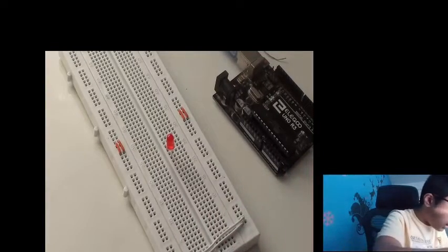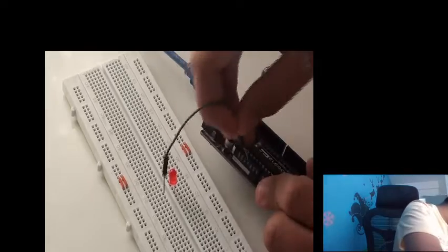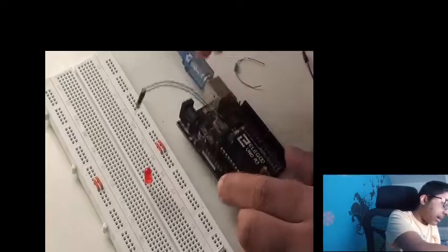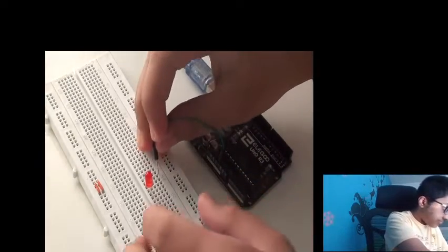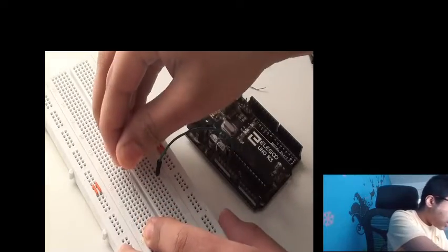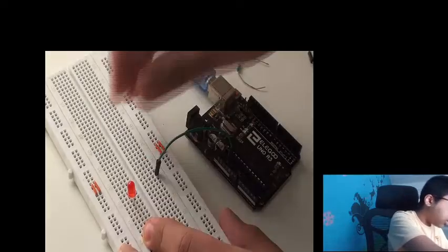What we are going to do is drag a 5 volt line from the Arduino. Now look at this. This is the 5 volt DC line. Okay, we are going to put a pin right onto that and we are going to stick it right onto there. However, if we do that, the LED is actually going to blow out. An LED cannot handle as much as 5 volts.